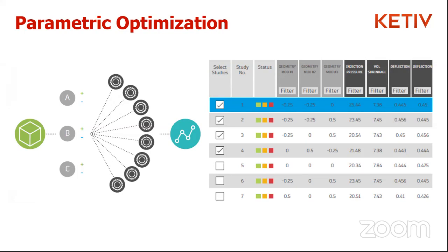Now, instead of manually adjusting each design variable as we did previously, with the example in the first or second slide, where the wheel hub that we had, we added gates to it, and then we saw that it added more weld lines, and so you tested that for strength, etc. Here in this case, you make your geometry changes, and instead of manually adjusting the design for every single variable, you can automate the analysis by defining a range of values, as we talked about.